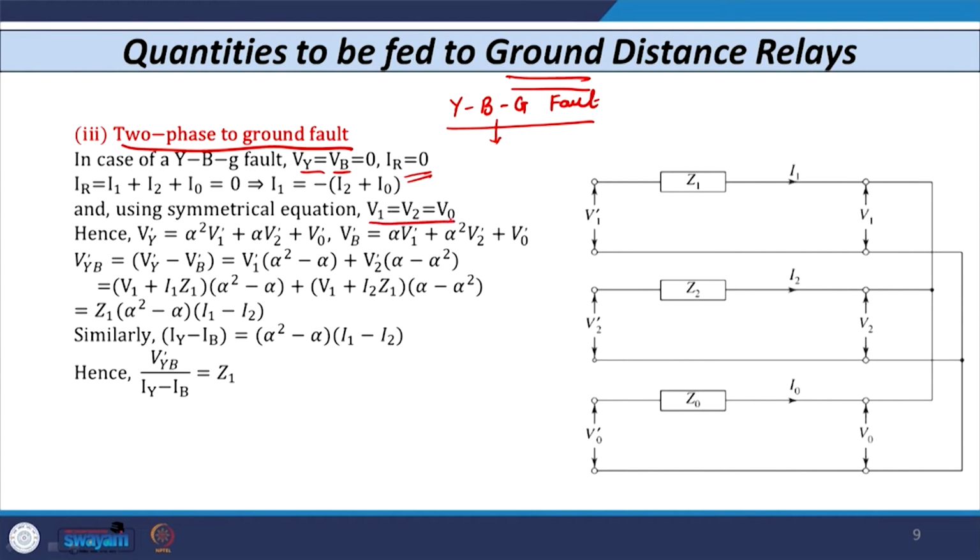So, all 3 sequence voltages, positive, negative and zero sequence, at the fault point are equal. This is the fault point.